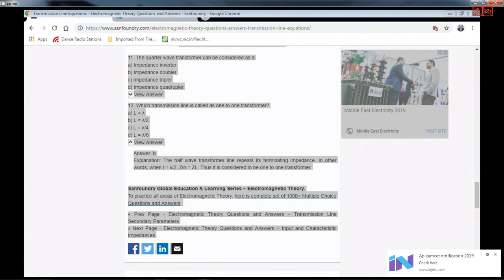That's why people don't specifically mention voltage standing wave ratio and something else as current standing wave ratio. Simply they say standing wave ratio. It means either of them. Only for the reflection coefficient will you have changes of sign, whether it is the voltage reflection coefficient or the current reflection coefficient. So let's not get confused with all that. In the present, we have only the voltage reflection coefficient, voltage waves, and voltage quantities, because we are still using electrical conductors like brass, aluminum, copper, etc.